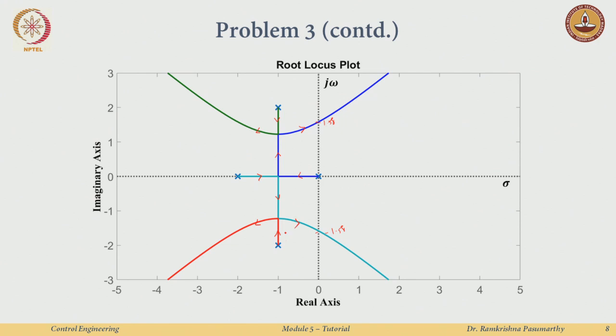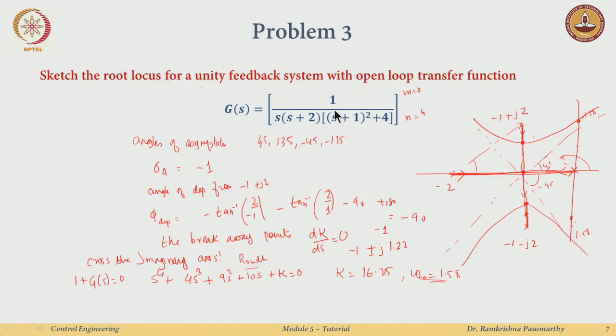So, we are just using all those steps to see the entire plot, and then see this intersection with the imaginary axis. So, I know that after some point, if I keep increasing the gain, the system might actually go unstable. It is not might, it will actually go unstable after my gain increases beyond 16.25. Okay, you could just do this in MATLAB.